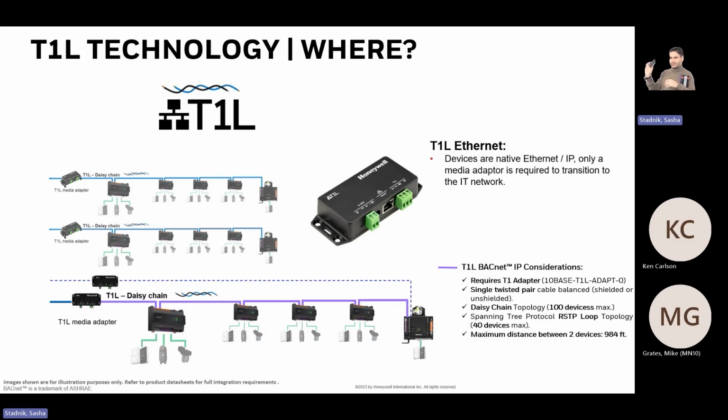So right now, if you purchase this one, it doesn't come anymore with a power supply. But also, what they were using this on the manufacturer, and they realized is VDC. Well, right now the only controllers in the world is a unitary and the VAV. Guess what we have as a power supply output on these two controllers? 24 volts VDC. So now you can power this thing with this one, and then you don't need the power.